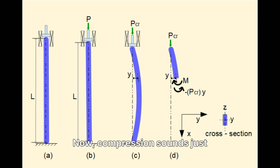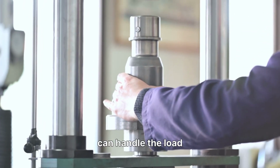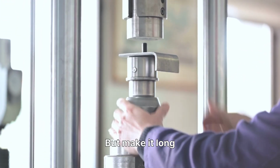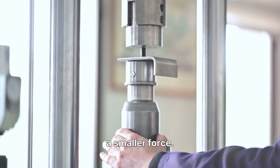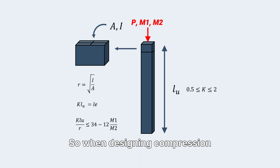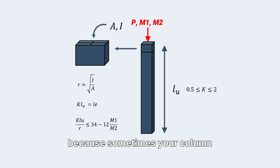Now, compression sounds just like the opposite, push instead of pull. But compression brings its own problem, buckling. If a column is short and stocky, it can handle the load easily. But make it long and slender, and it can suddenly bend and fail, even under a smaller force. So when designing compression members, you don't just look at the material strength. You also check the slenderness ratio, because sometimes your column won't crush, it'll buckle.